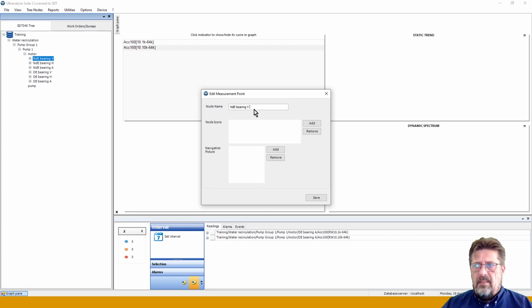Is this bearing sealed, or is it being greased? It's being lubricated. Is it lubricated with oil or grease? So if it needs to be lubricated, why not just put a small L here? So it is lubricated. It's not a sealed bearing, so somebody needs to take care of it. And if it's lubricated with grease, why not just put LG? So saying yes, it's lubricated, and yes, it's lubricated with grease. I'm doing this because later on I can really easily filter out all my bearings which are lubricated with grease, as opposed to all my bearings which are sealed.